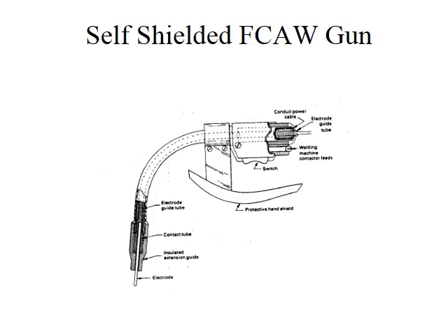Generally, the self-shielded flux-cored arc welding electrodes are in sizes larger than those of the gas-shielded flux-cored arc welding process, and thus run at higher amperages and voltages. This means that there is more heat going into the glove of the welder, hence you need to shield his hand to protect it from damage and injury. So that's the reason you've got the protective hand shield on this gun: higher amperages and voltages.